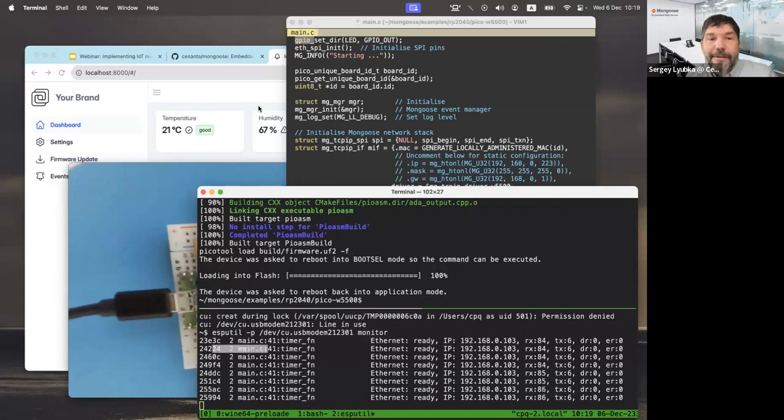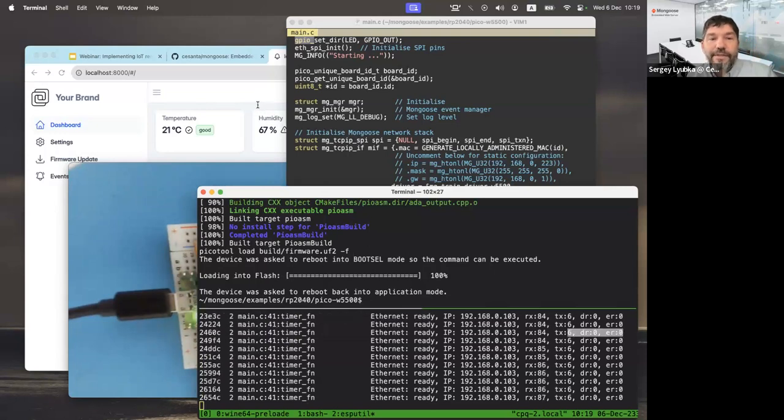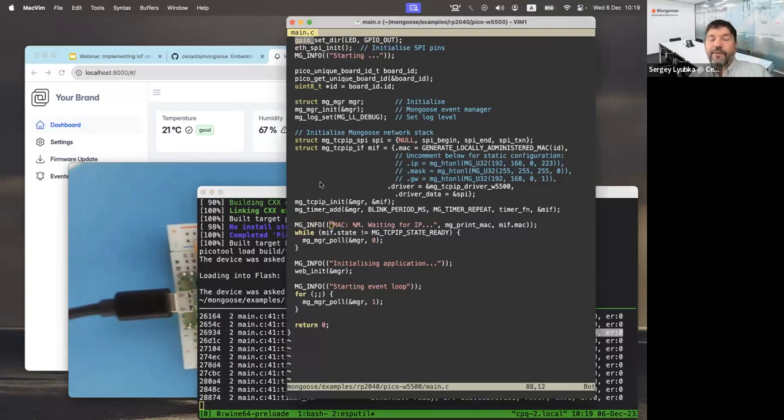I have a question. Roy is asking, why does the for loop use a 1 millisecond poll rate and not 0? Well, the thing is that when we use the bare metal implementation and the embedded TCP/IP stack, this second parameter is really at the moment just ignored. It doesn't matter what we put here, 0, 1, it could be even int max, right? It does not really matter.